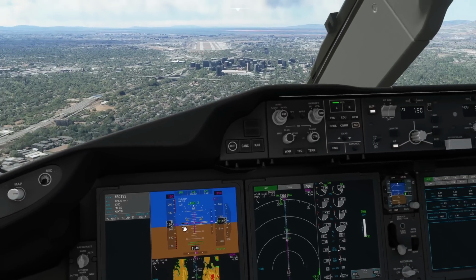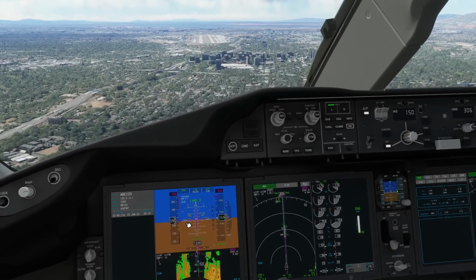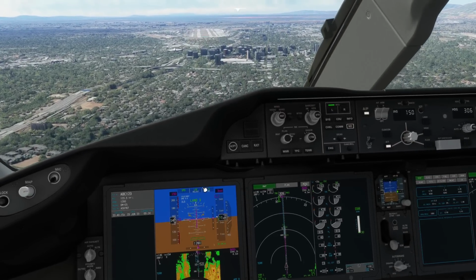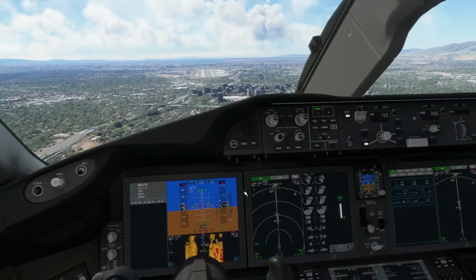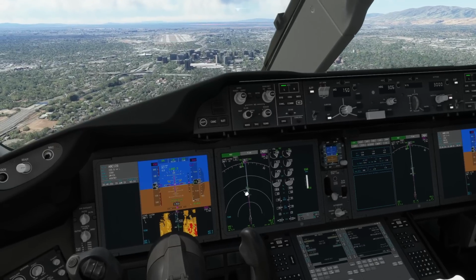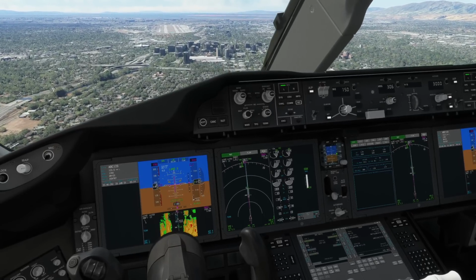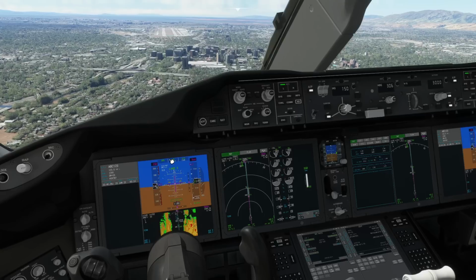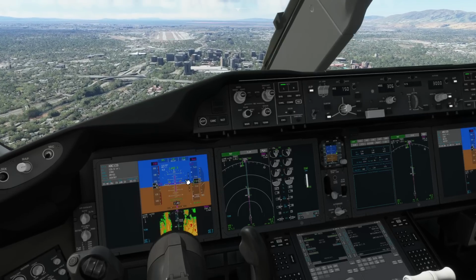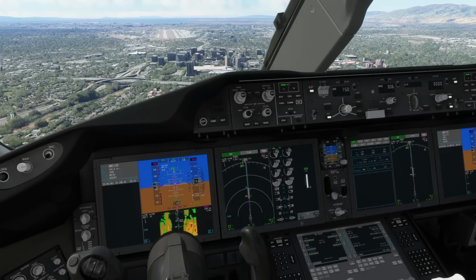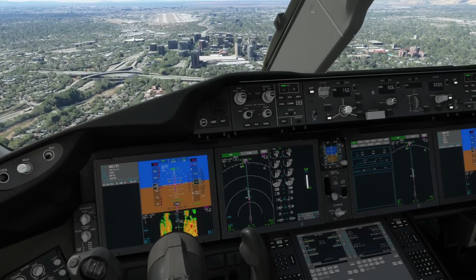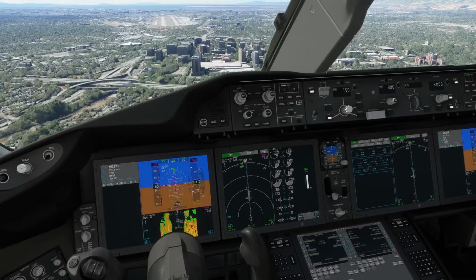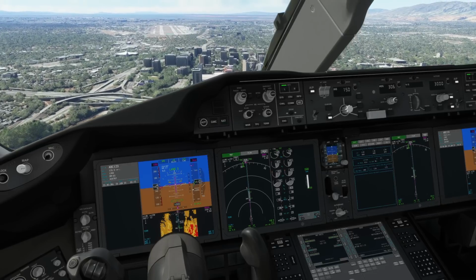So maybe that's a function of this aircraft, and certainly somebody will probably comment on this about the technicalities of Cat 2 and Cat 3 and whether some aircraft can do a full auto land. So localizer's gone to rollout mode, glide slope's gone to flare mode, so it will do the full auto land, even on a Cat 2 ILS. Whether that's realistic, I don't know.